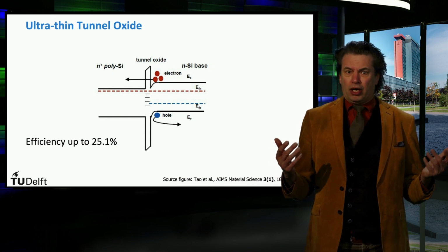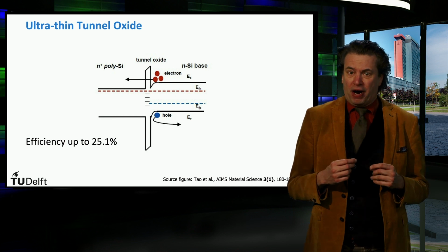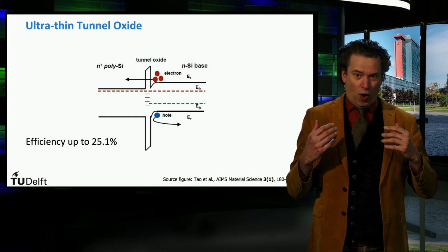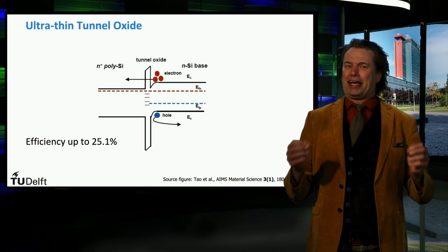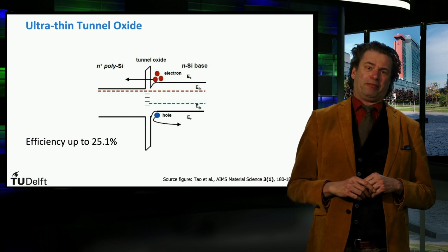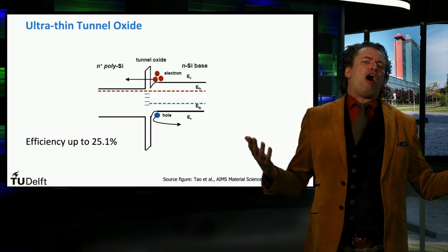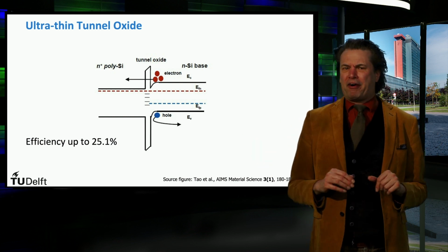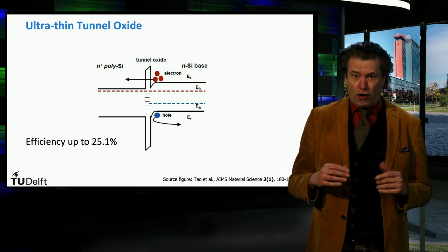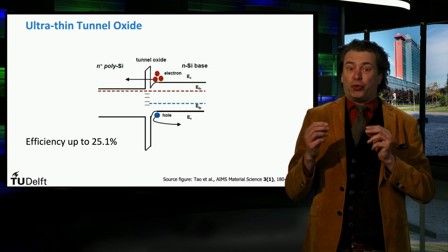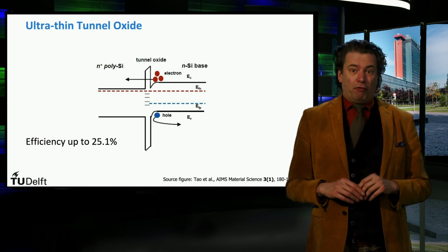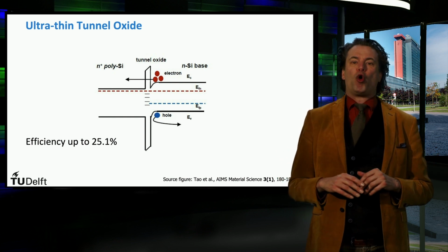In contrast to classical mechanics, in which a particle cannot move through such a barrier, in quantum mechanics this is possible, since this oxide layer is kept very, very thin. A large fraction of the electrons can move through this barrier, and this phenomenon is called tunneling. Therefore, electrons are able to tunnel through the barrier and be collected at the back contact with virtually zero loss.